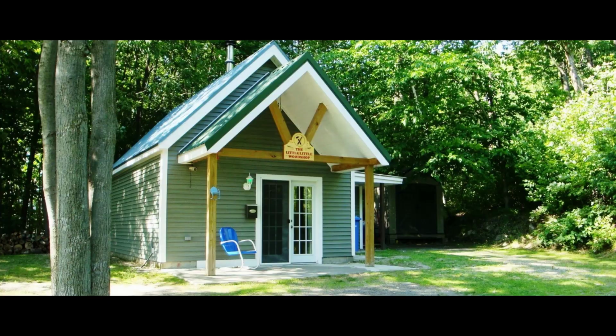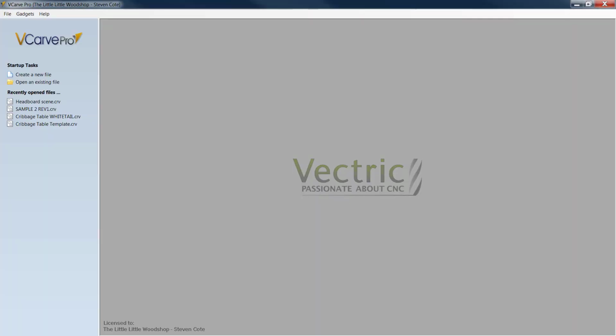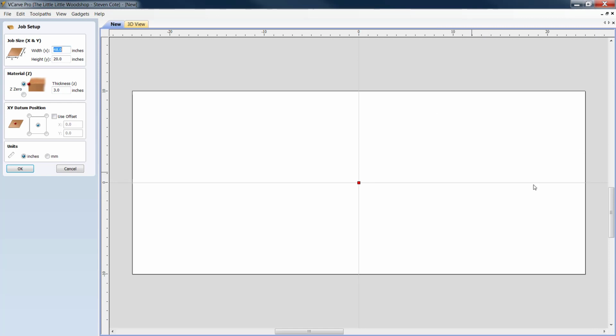Alright, let's get started. I'm going to bring in a copy of VCarve Pro and create a new file, and my old presets are in here. Now I told you the maximum capacity on my machine is 50.249. However, as I told you in the introduction of this video, which we shot a couple days ago, we're going to program this on the X. We'll end up rotating it when the design is all laid out. We have to rotate it on the Y so it will then fit under the gantry, because my machine is 48 by 36.